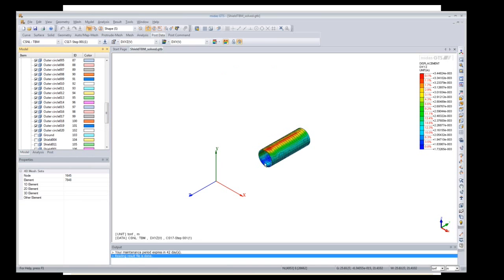Show only, so you can see the results only for these members throughout the construction staging. From 0, you can see how the members are removed, and then the segment members are installed. So you can find out the forces in these members directly, like this.